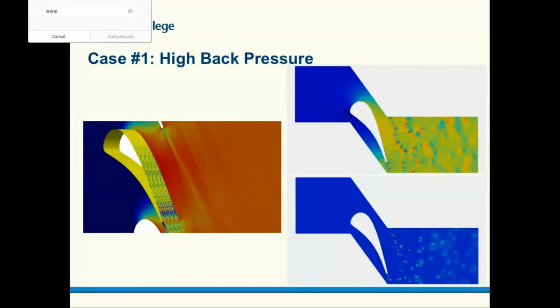So there are 2 flow conditions we considered. This is the first time we ran these particular cases with the flow solver Nektar, which is a high order spectral/hp element, right? So it's a finite element solver. We decided to opt for 2 different conditions with clean inflow. That means you have no inflow turbulence. And one is a low suction, so you have a very high back pressure. You can imagine high back pressure means that you're not sucking the flow out, you're not making it accelerate that much. So this is a more common flow condition, and you can see the flow you have here.